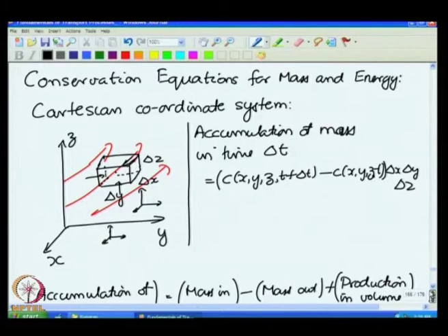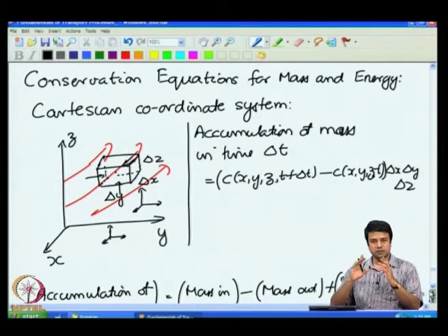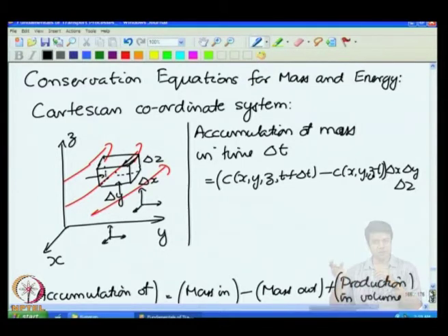The convective transport is just equal to the velocity times the concentration itself, because the flux due to convection is equal to the concentration, mass per unit volume, times the velocity, which is length per time, velocity perpendicular to the surface. Multiply those two, it gives you mass in per unit area per unit time, which is similar to a flux.